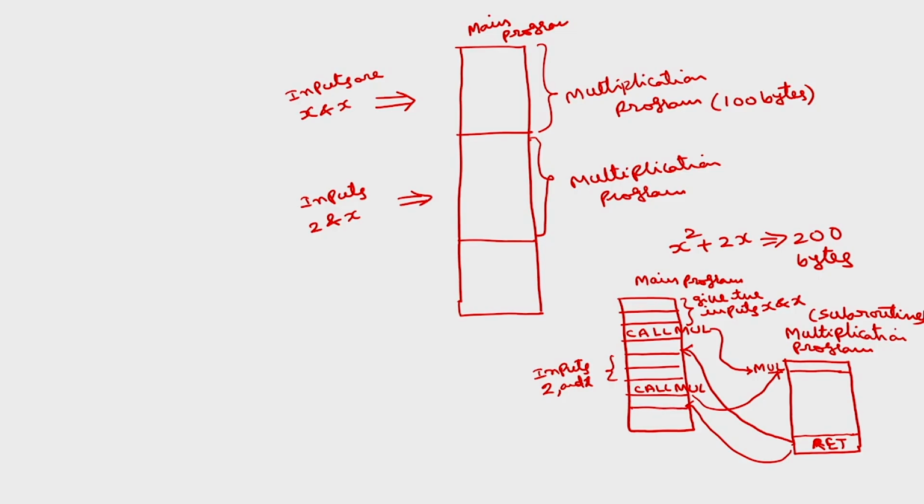But here the problem is, whenever the microprocessor is executing this call instruction, the instruction which is to be executed next is this. So, the instruction pointer will hold this address. Suppose the offset of this particular memory location is 6000H, the instruction pointer holds this 6000H. Then if I do not save the instruction pointer contents and I go to this subroutine, while returning, how does the microprocessor know that it has to return back to this 6000H? So, that is why this 6000 location has to be stored in some temporary location which is called the stack.